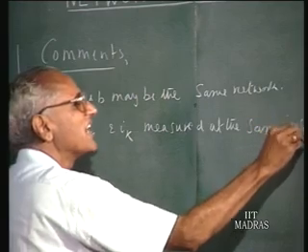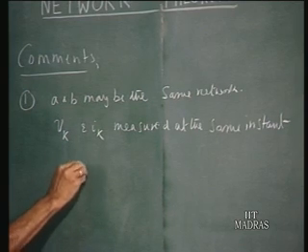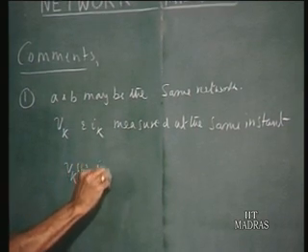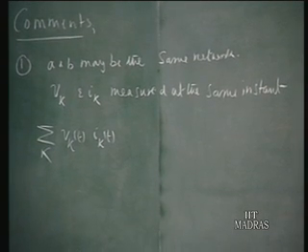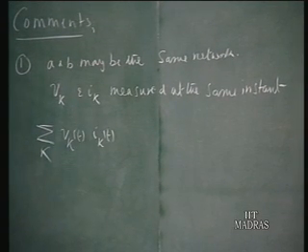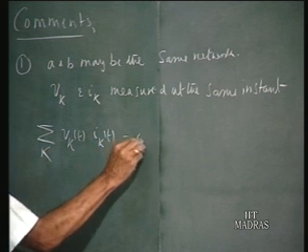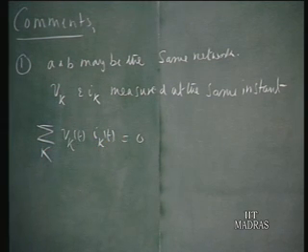So if you take the currents and voltages at the same instant, Tellegen's theorem says Vk(t) times Ik(t) summed up over all k is 0. After all, there is no point in now saying A and B because it is the same network. This is a statement of conservation of power in the network.